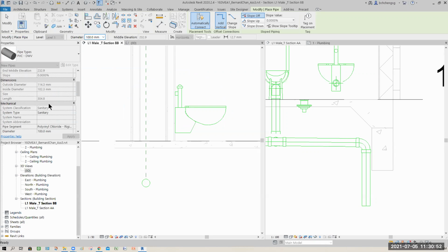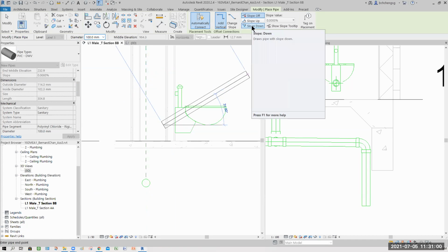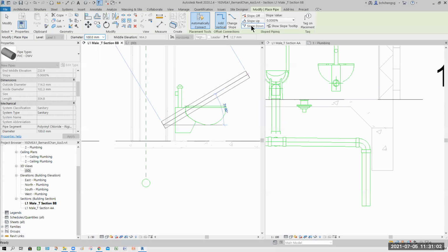and PVC after that, scroll down to check it must be sanitary. Okay, so this part here, it should be what? Slope down, right? It means you can tilt a bit to ensure that it helps the flow faster. If it's horizontal, sometimes when you flush, the flow might not be fast enough, in the sense that it might bounce back, because sloping is no matter what faster.